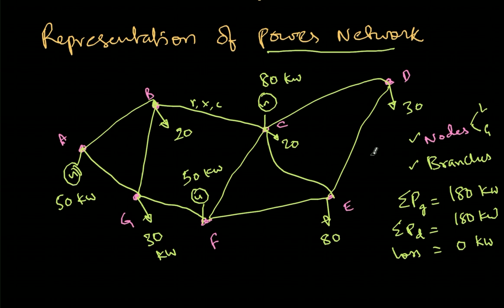Now the issue is, here the 30 kilowatts of load is there. Of course we are all talking about an AC power system. So not only kilowatts, there will be kVAR also, or reactive power. So this is 30 kilowatts of load, plus j10 kVAR of reactive power demand might be there. Similarly the generation also, it's not purely active power, it could be generating reactive power. And similarly again, the sum of total reactive power generated should be equal to total reactive power consumed.